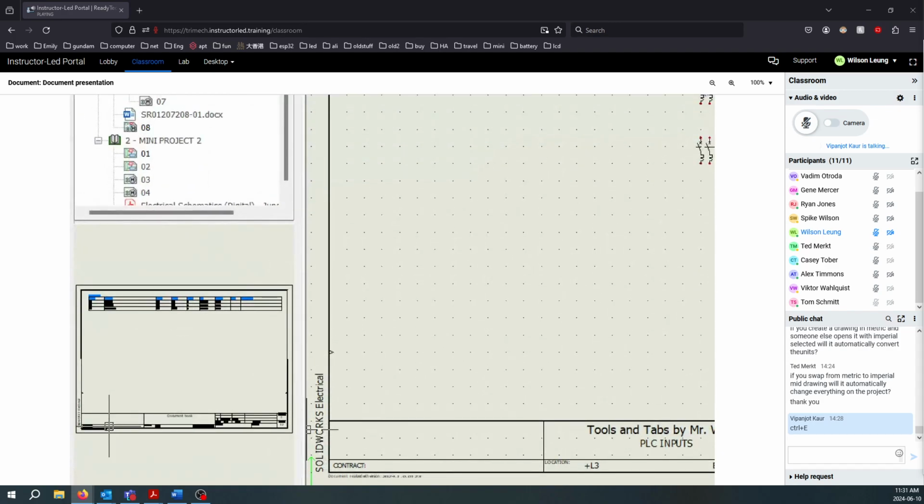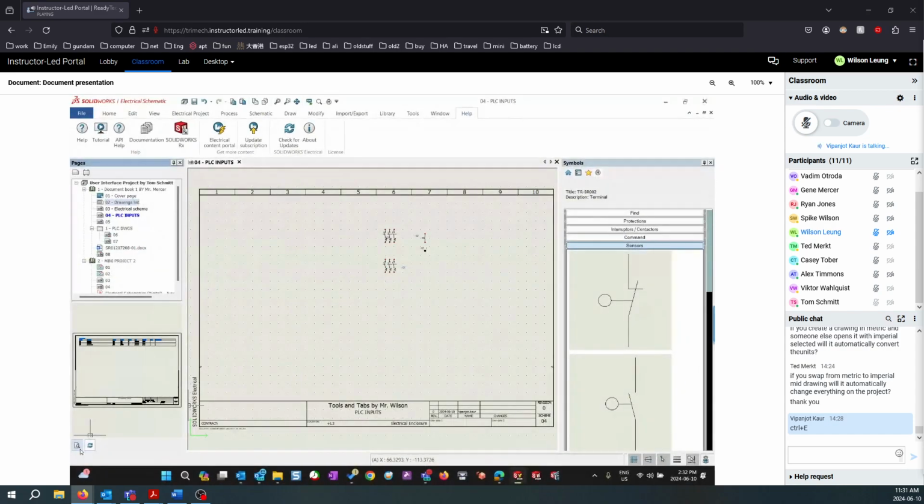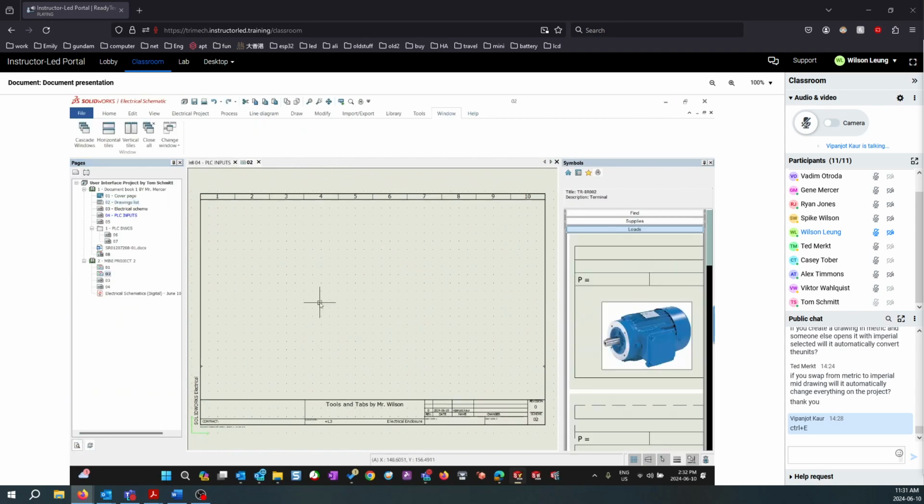So a lot of people complain, "Vip, I was clicking on a drawing, it took 5 minutes to open up, it's running in circles." It's because you have this preview window on, which is wasting your time loading the preview first. So I like to click on this first button, keep it off, so that I can simply double click and open the drawing. Don't waste time in the preview for me. So I uncheck the preview and turn it off.